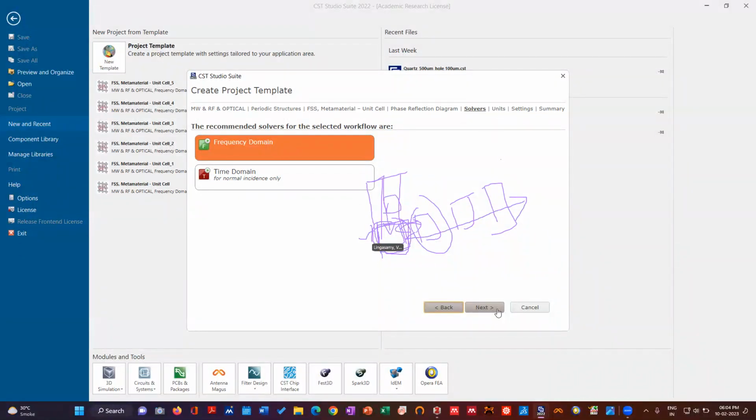The other method is, for example, you can use a TEM waveguide. TEM means? TEM waveguide. Usually a waveguide will have a TE mode like this, correct? TE10 mode waveguide. But if you want to have both the E field and H field orthogonal to each other like this, TEM waves, we cannot make this one. So one wall will be an electric wall, the other wall will be a magnetic wall.